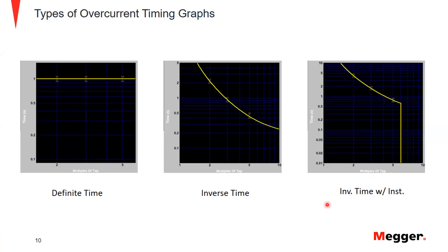The instantaneous element that's tied into the inverse time characteristic as well is very effective in reducing operate times of severe faults. They don't offer any selectivity because they do have different characteristics, and they're instantaneous for a reason: we want to make sure that we get the fault current off the device in the yard as quickly as possible to minimize damage.